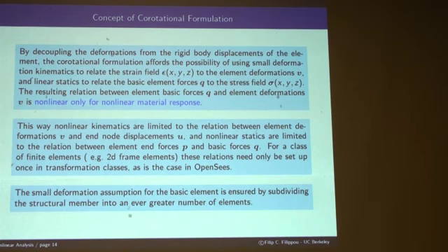This way, nonlinear kinematics are limited to the relation between element deformation V and end node displacements U. And nonlinear statics are limited to the relation between element forces P and basic forces Q. So I'm only doing it at the discrete level, at the end nodes. I don't have to do it inside the element.